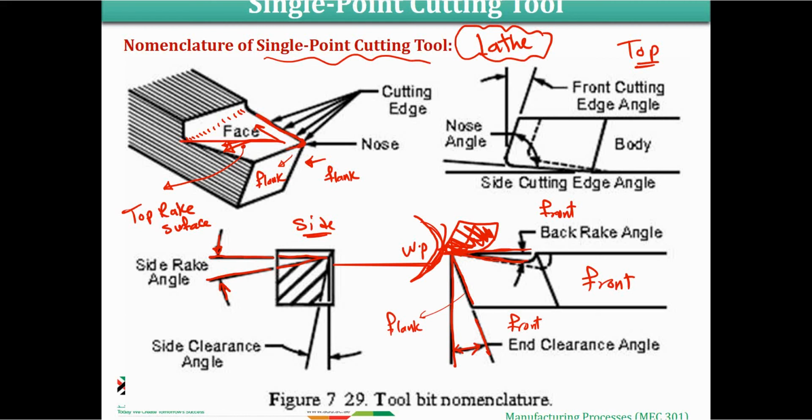So that's why we are achieving two inclinations, one in the front, one in the side. The same thing, this clearance angle is needed to eliminate the rubbing or the friction between the tool and the workpiece. But if we don't have this friction, definitely we're gonna end up with more heat that shall be generated. So to eliminate this friction, also to allow for removing the heat